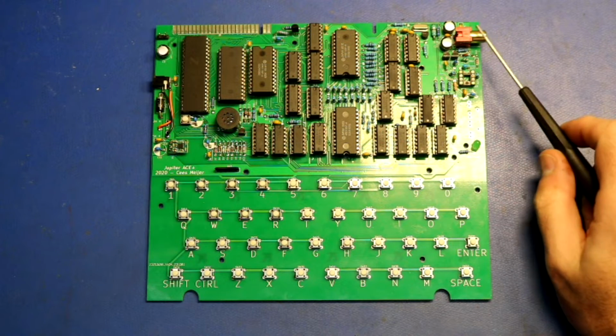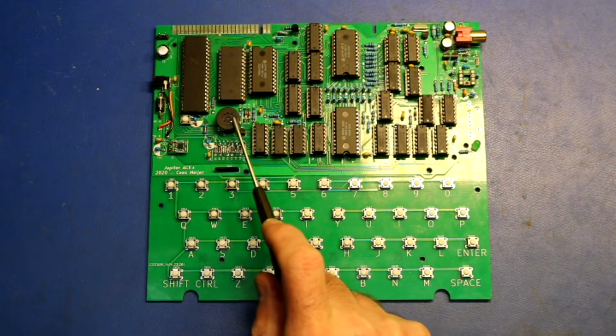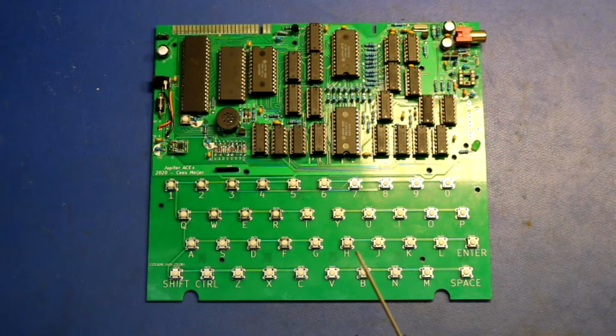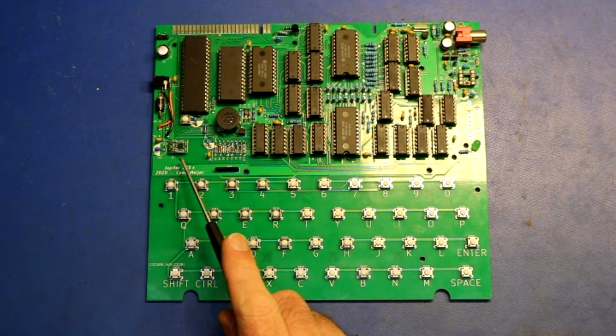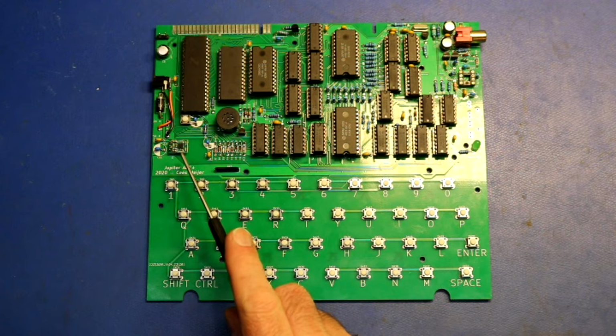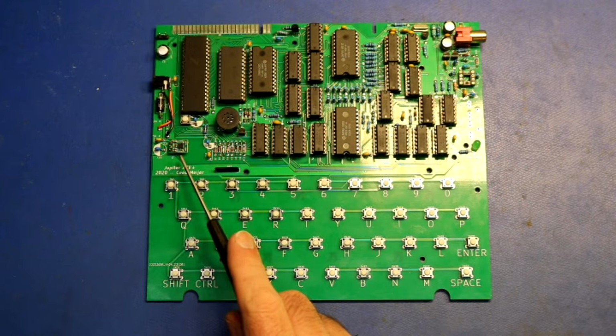You've got your video out here on the side. It does have an onboard speaker. I used this little round speaker that I got from Mouser for another project. Over here would be your voltage regulator. So I used a Pololu step up, step down regulator because it will regulate all the way down to 5 volts, even a little bit below 5 volts, and still give you the 5 volt output. So it will either step up or step down as appropriate.